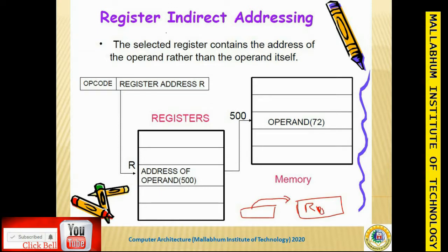But in the register indirect addressing mode, this is your opcode and this is your operand, say R1, and this operand holds the address, and within that address the value is accessible. Suppose R1 contains 5000, so the processor goes to location 5000, and if the data within that location is 05, then that data is accessed.